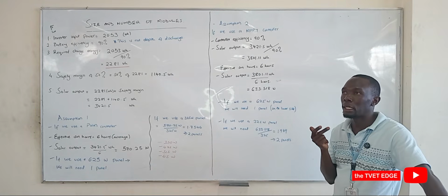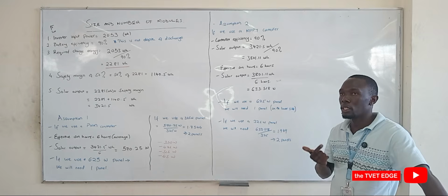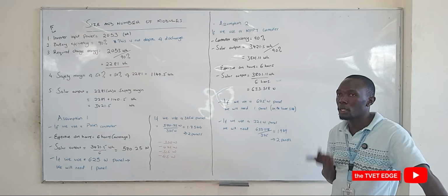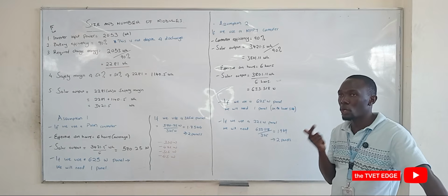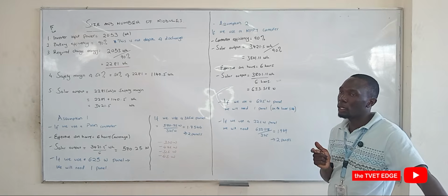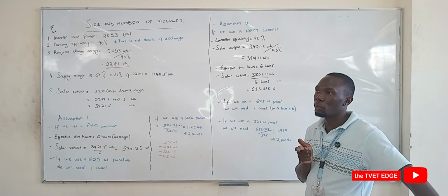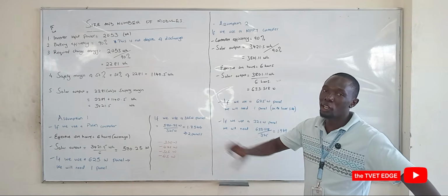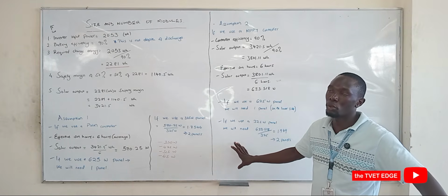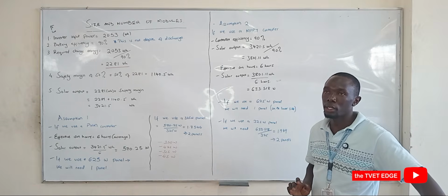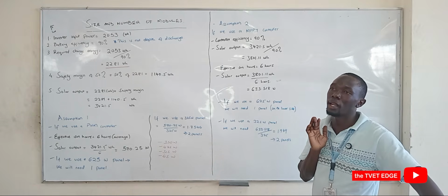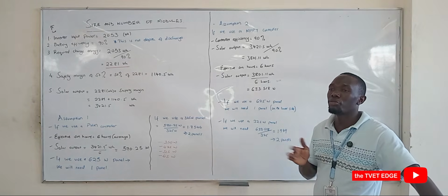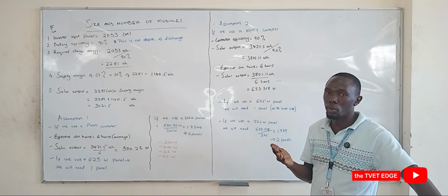For the cables, I'll encourage you, use 6 squared millimeter flexi or solar cables or DC cables. 6 squared millimeter double insulated solar cables, flexi or solar cables, whichever term you'll remember. Use 6 mm almost all across the system. For you, the 6 mm cable will work. Between the inverter and the batteries, you can go even higher. You can utilize 10 squared millimeter cables. If the client is okay, go even for 16 squared millimeter cables.